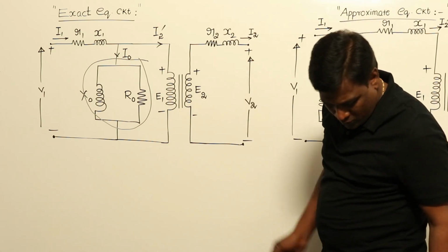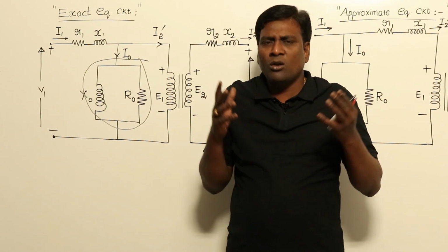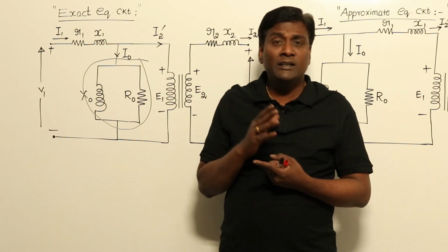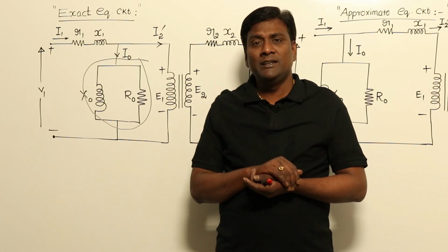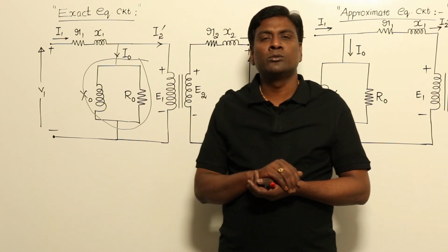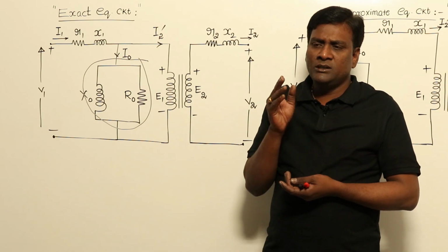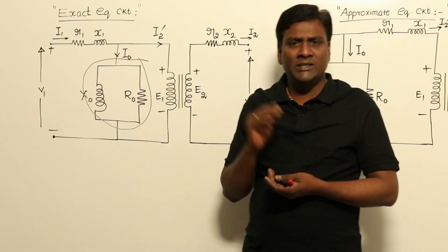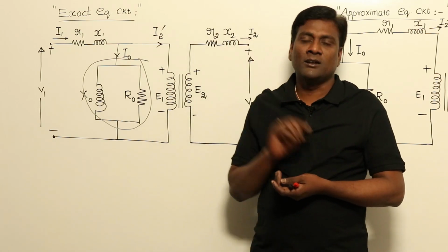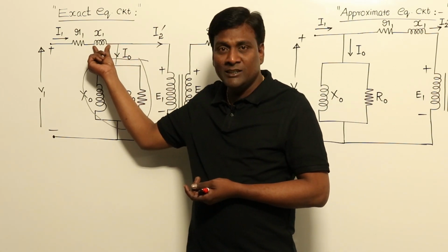Okay, now about leakage, actually we may have to discuss many concepts about leakage. Many people feel that leakage is lossy, or that leakage influences efficiency. No, leakage is actually a lossless quantity. About this, in the detailed course of machines I will discuss, but anyway keep one point in mind: leakage is not lossy, because leakage is being modeled as an inductive reactance.